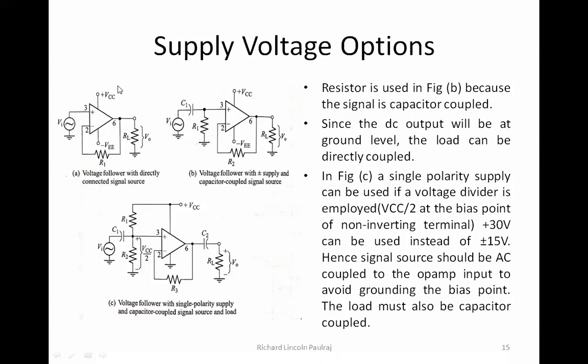Yes? Yeah. So do not get confused with both of these plus. This plus and minus is needed to power up your op-amp, to turn on your op-amp. And this plus and minus is the inverting and non-inverting terminal of the op-amp, which accepts the input signals. So do not get confused.